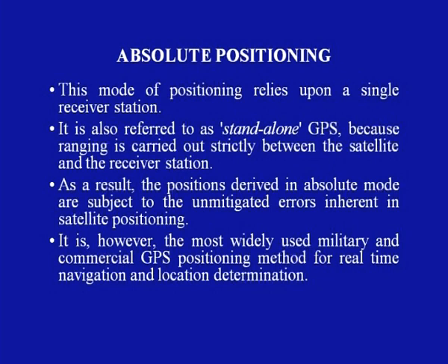In this mode of positioning, it relies upon a single receiving station. This is also referred to as a standalone GPS because ranging is carried out strictly between the satellite and the receiving station. As a result, the positions derived in absolute mode are subjected to unmitigated errors inherent in the satellite position. It is, however, the most widely used military and commercial positioning method for real-time navigation and location determination.